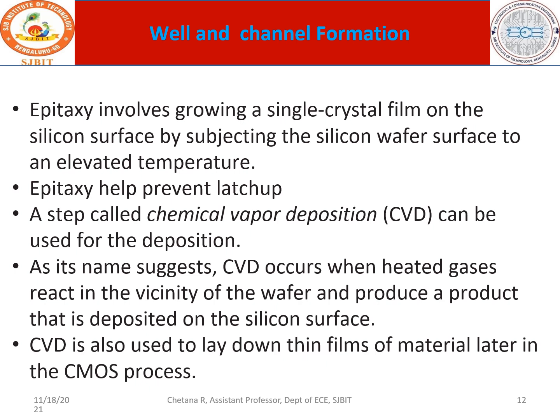What exactly is an epitaxial layer? We have a single crystal film on the silicon surface, and you heat the wafer to a high temperature. Then a thin film of this crystal gets deposited, and that forms the epitaxy. So the epitaxial layer prevents latch-up. The latch-up phenomenon is the creation of transistor junctions inside the substrate. So once you have the epitaxial layer, the transistor terminals are broken, and as a result the transistor junction is not created and you don't have the transistor effect.